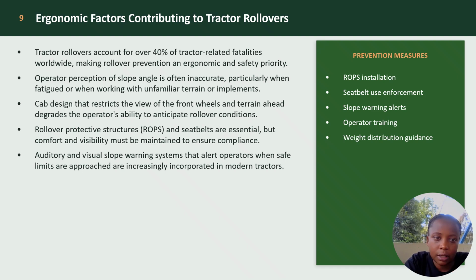Cab design that restricts the view of the front wheel and terrain ahead degrades the operator's ability to anticipate rollover conditions. Rollover protective structures and seat belts are essential, but comfort and visibility must be maintained to ensure compliance.